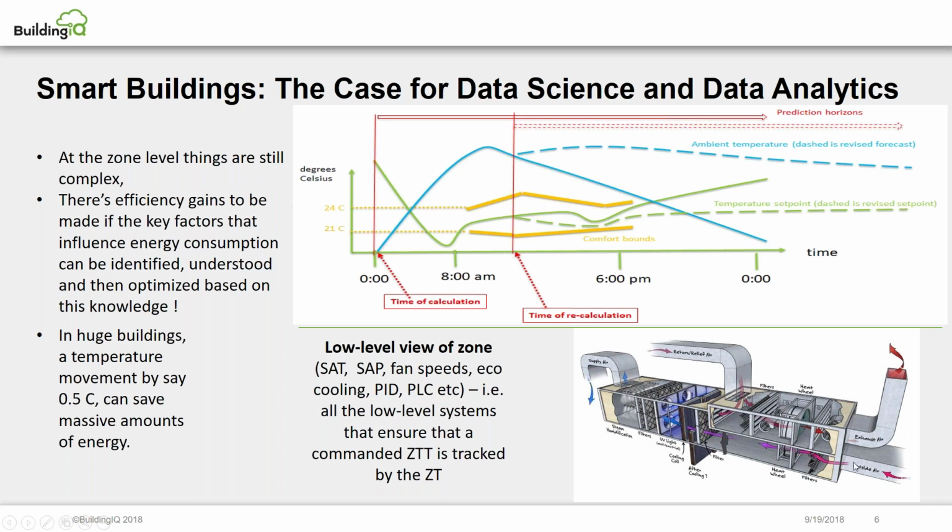And then if you need some further cooling, you lower down the temperature and send it through extra filters and then through the supply air ducts to the zone. So the operation is not easy, but what we have is a smart control strategy that looks at so many variables. So we look at the cost of the energy, the weather forecast, and so many other parameters, as I will show you in a second.